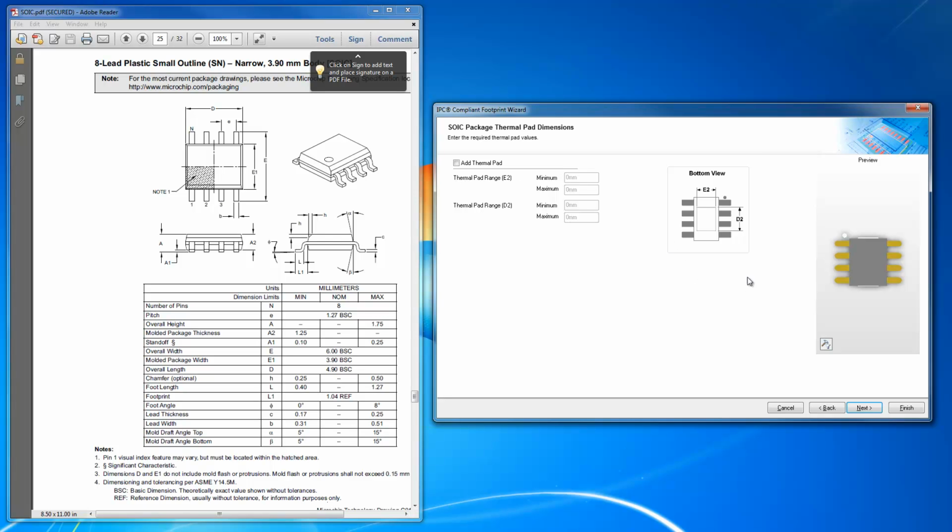Now, one other thing I'm going to mention as we're going along is if you want to see some more information here, you do have the ability to modify this and move it around. So for example, if you want to see how the underside of this looks, well, you basically use the same command set that you'd normally use if you're in 3D. So on my keyboard, I'm going to hold down my Shift key. I am going to right mouse click, and that's normally what you do in order to rotate it.